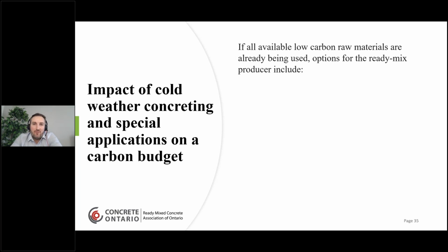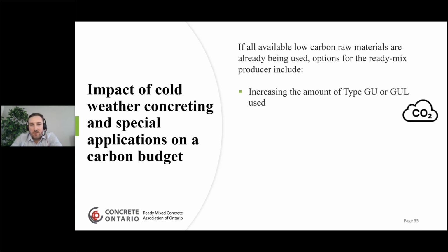So if you use all available low carbon raw materials, the ready mix producer has the following options to achieve some of these special applications, to achieve some of these cold weather concreting solutions. They have to increase the amount of type GU or GUL used. You're getting better performance in cold weather, which again drives up the CO2 footprint of that mix design.